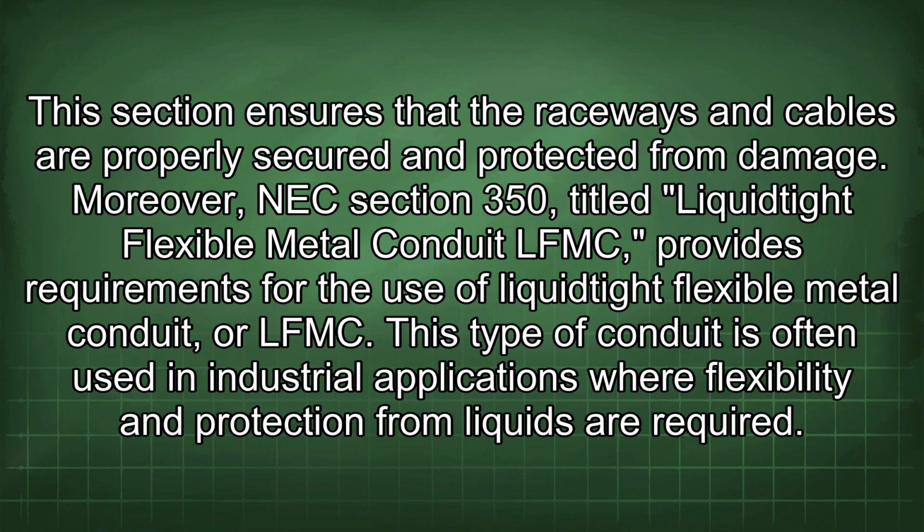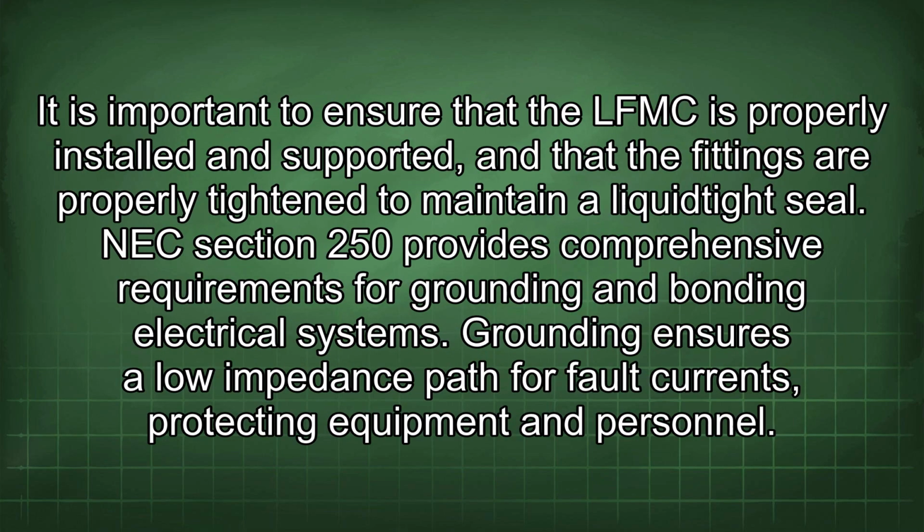Moreover, NEC Section 350, titled Liquid-Tight Flexible Metal Conduit, LFMC, provides requirements for the use of liquid-tight flexible metal conduit, or LFMC. This type of conduit is often used in industrial applications where flexibility and protection from liquids are required. It is important to ensure that the LFMC is properly installed and supported, and that the fittings are properly tightened to maintain a liquid-tight seal.